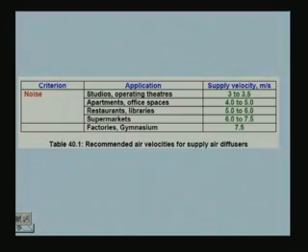So, that is how the supply air velocities are decided or selected, depending mainly on the noise criteria, which in turn depends upon the application. You can see here that these supply air velocities are much higher than the required velocities in the occupied zone, which lies between 0.15 to 0.36 meters per second. So, the supply velocity is at least one order of magnitude higher than the required velocities in the occupied zone.